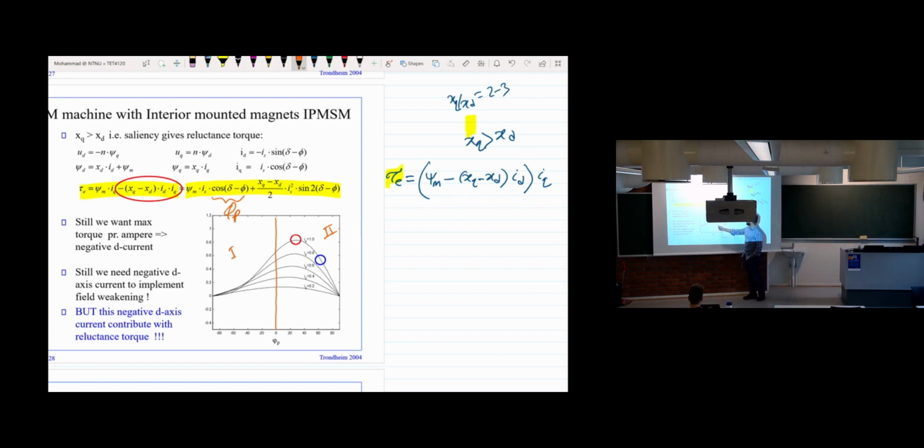If we put the angle at this position for this current, you can get the maximum torque. For example, here, we can have the maximum torque if we provide 1 per unit. But if we want the torque not at this location, it's possible if we provide the angle, this PP, at this position, then it gives us this torque, which is much less. So we always try to operate somewhere here so that it can provide the maximum torque if necessary.